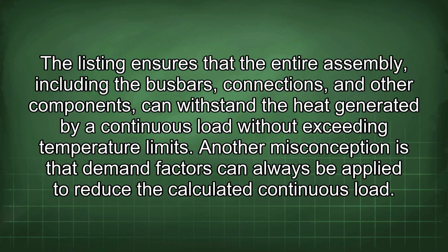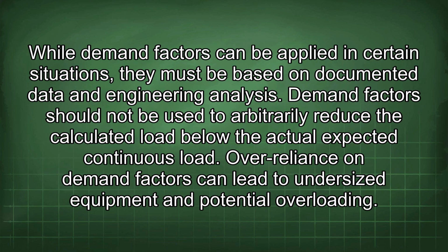Another misconception is that demand factors can always be applied to reduce the calculated continuous load. While demand factors can be applied in certain situations, they must be based on documented data and engineering analysis. Demand factors should not be used to arbitrarily reduce the calculated load below the actual expected continuous load. Over-reliance on demand factors can lead to undersized equipment and potential overloading.